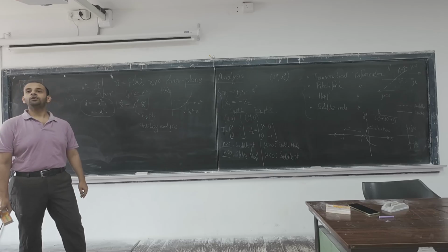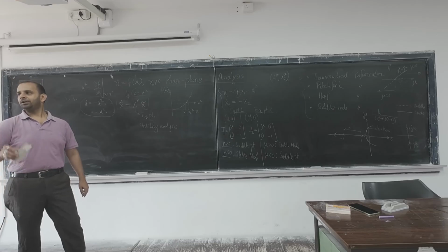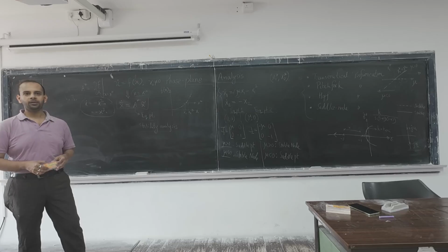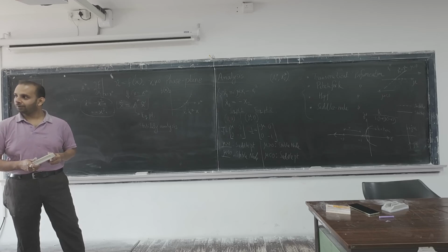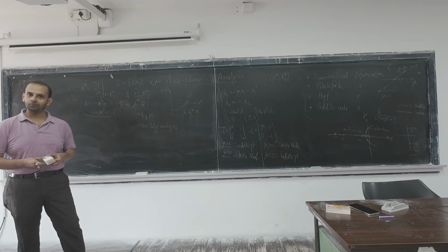Of course it will be for a certain range. That is, the stability properties are local, which you have now understood. The next question is: when we design a controller, will that also be local in nature or global? Yes, that will also be local, because suppose you have linearized a nonlinear system with respect to an operating point. Now you have a linear one.